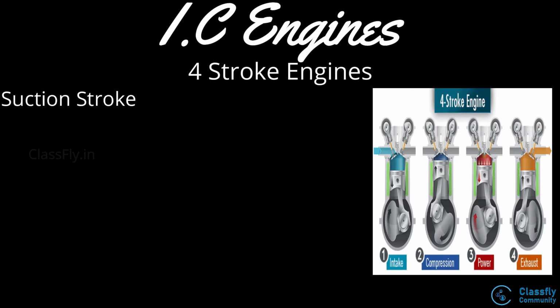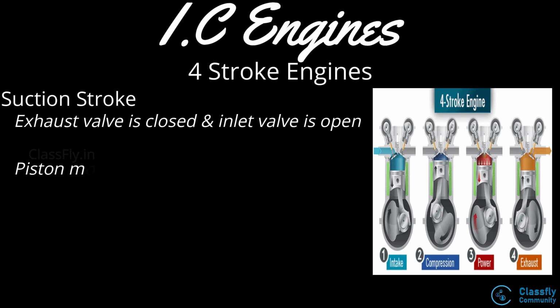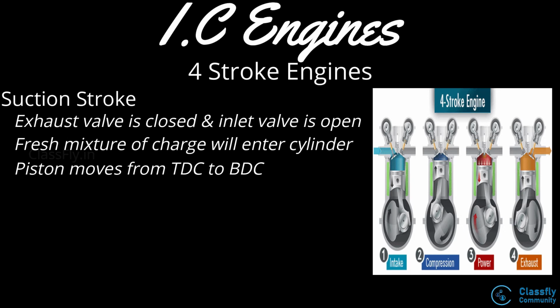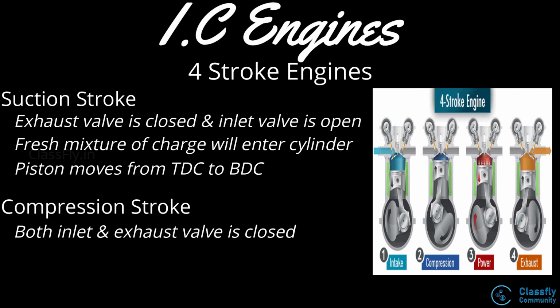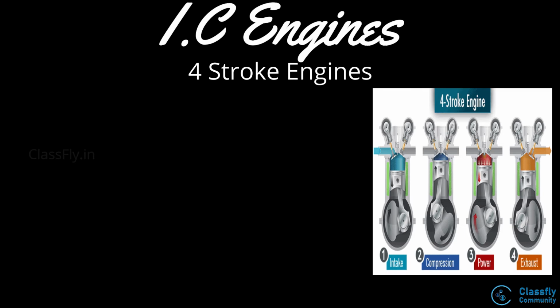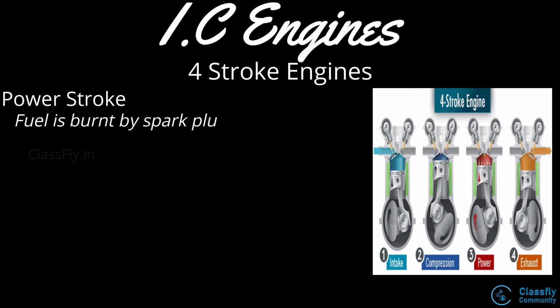Then we studied about the construction and working of a 4-stroke engine. Well, the 4-stroke engine will have 4 strokes, that is the suction stroke, where the exit valve is closed and inlet valve is open, and hence a fresh mixture of fuel and air will enter the cylinder. The compression stroke, where both the valves are closed and the piston will move from the BDC to the TDC, hence compressing fuel.